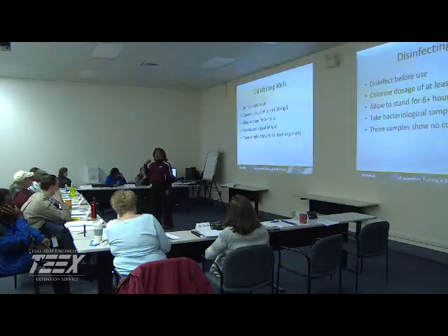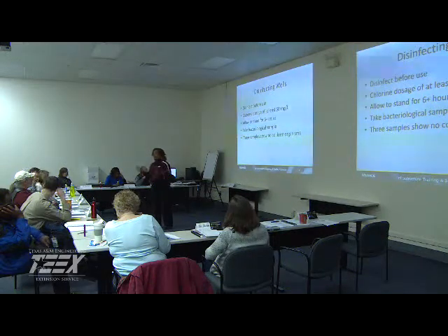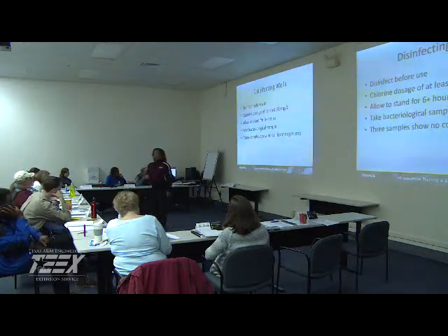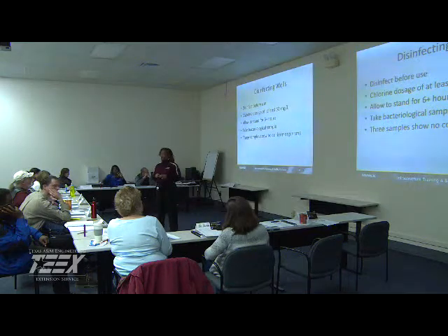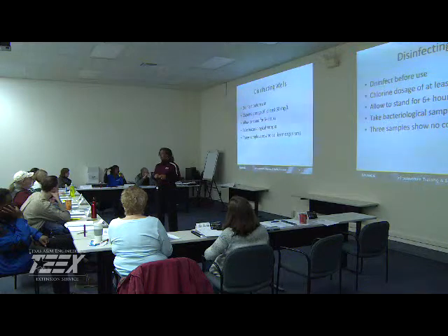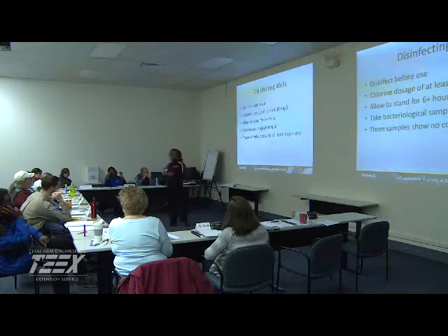I thought they were supposed to do 200 milligrams per liter. Again, there are different methods of disinfection, and you choose which one works best for you. At the time, if you had a higher concentration. Absolutely. Sometimes you have to go back 5 and 6 times before it works. You have difficulty with new wells. Really? At 200 milligrams per liter? You got high pH, it's hard to disinfect. Wow.